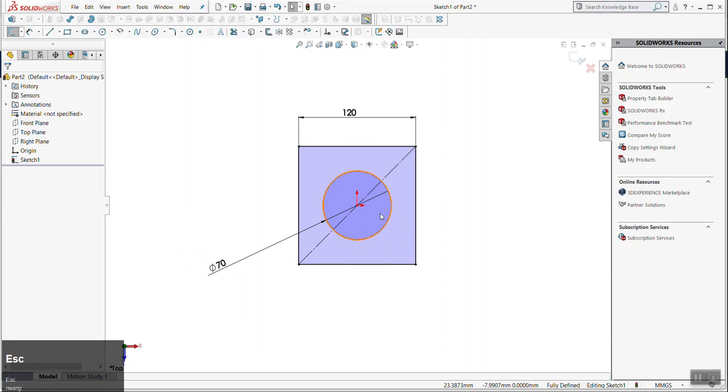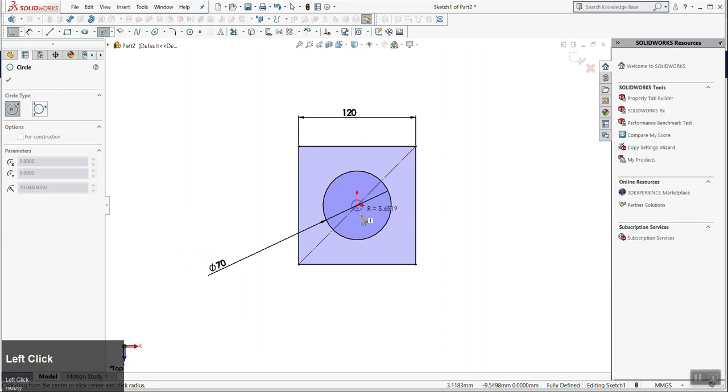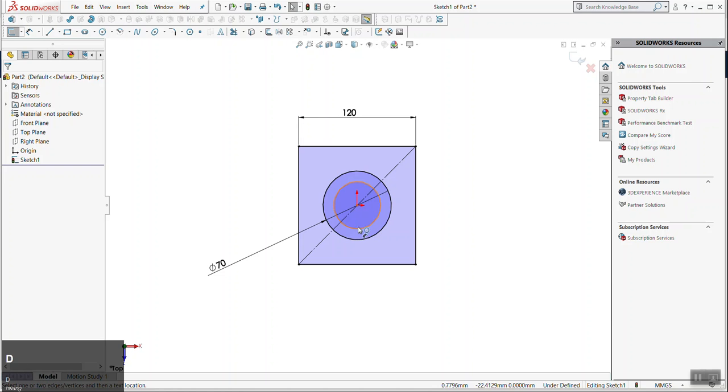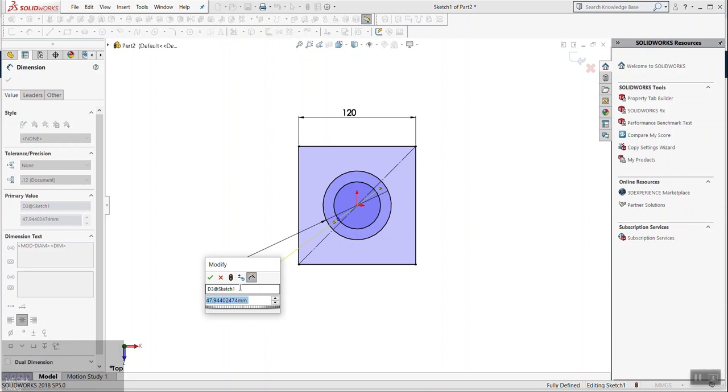Now I know I'm going to have to cut a hole through this. What I'm doing right now is I'm creating the master sketch. I'm creating all of the measurements that I need to create the part in one sketch. This is so that all the information is located in one area if you ever need to make an adjustment. If you reference this sketch for all of your commands, it's just a very tidy way to organize your build so that, again, if anyone is working on this model, they can go to the master sketch, edit that to change things, okay?